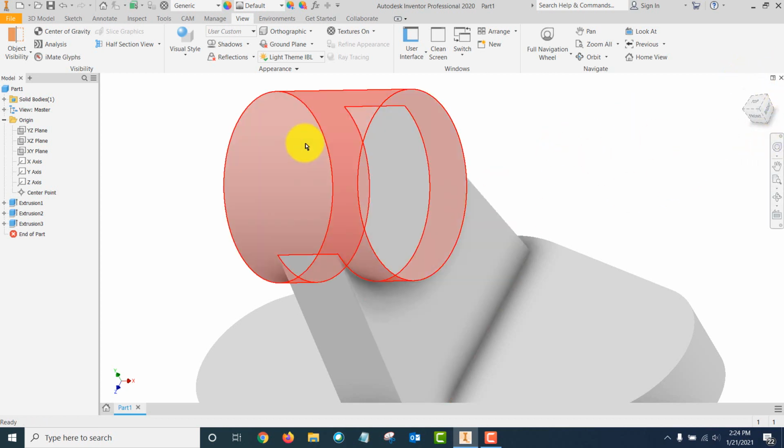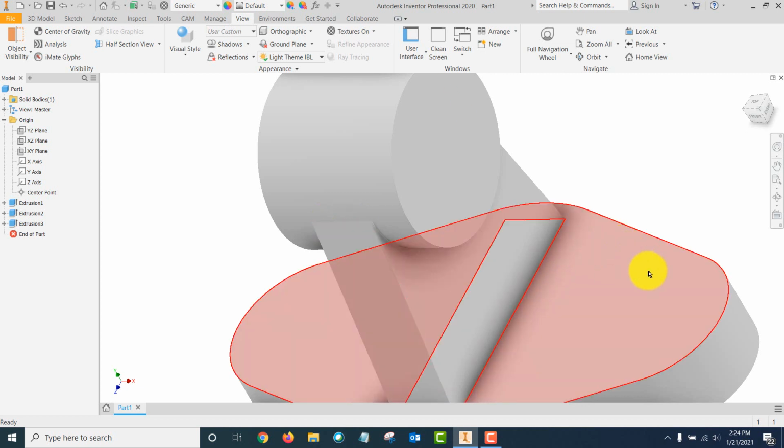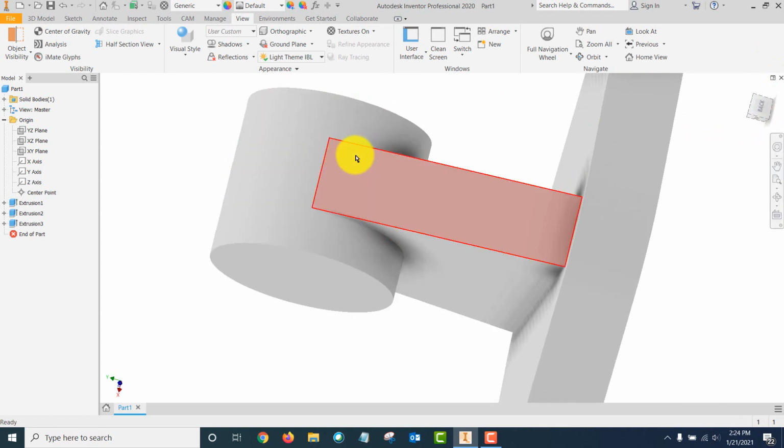So if you're looking at an object, whether it's an image or in the textbook or something like that, and you see a line and there's no other line shown, on tangent thingies like fillets and rounds, then you know that line is not tangent between the two faces. Whereas over on this side, under a normal view, there is not a line, so you know that those two faces are tangent. Because some of the objects that are similar to this that you're going to be drawing will have this upright tangent to the cylinder.